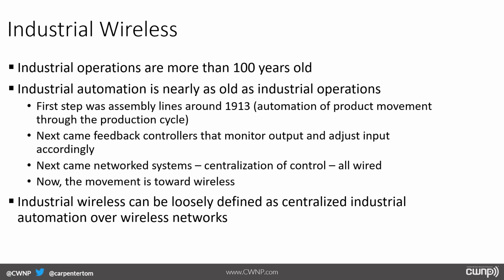You went up to it and you looked at the temperature gauge. Okay, so it was manual. If I can get the data from that temperature gauge to some remote location that I can see 50 temperature gauges for 50 different boilers, then I have automation. I don't have to manually go around to all of them anymore, right? It's being brought to me centrally.